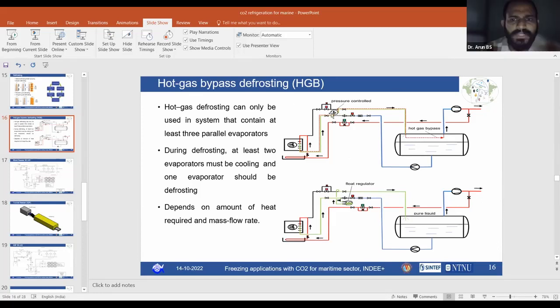How will it flow? It is not pumped. It is going back, this is the route. This is the path. Can you see my mouse pointer? Okay, I'll put it this way. Your hot gas inlet is coming into the drain pan. From the drain pan, it defrosts it, then goes in, and it's a top feed evaporator. That's why you are injecting it in the top. Now, the liquid vapor mixture will come back.